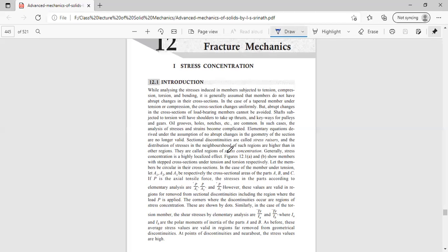Just known as stress concentration itself. This is called stress risers itself. The size of the shaft can be, say, like this. There is a shaft like this of certain length. And here there is a cross section like this. The reduction in cross section, then it goes like this. This type of reduction generally causes the action of stress concentration, and this type of small discontinuities are generally defined as stress risers itself.